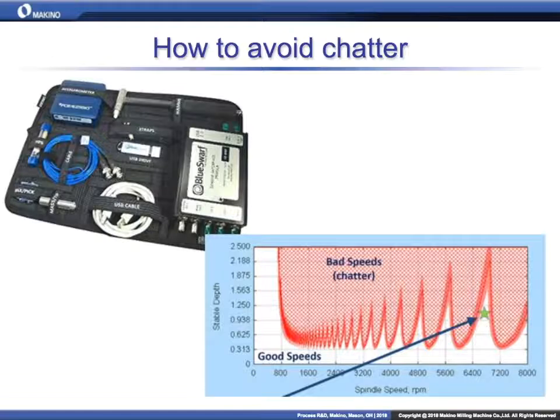We'll use an accelerometer, which is a device that will measure the acceleration. So we attach the accelerometer to the tool so that the accelerometer moves with the tool. So as the tool vibrates, so does the accelerometer. And that accelerometer gives us the information we need to determine what the tool's natural frequencies are. Because we know how much we excited the tool, and we measured what the tool did after we excited it, we can extract useful information about the tool's natural frequency.